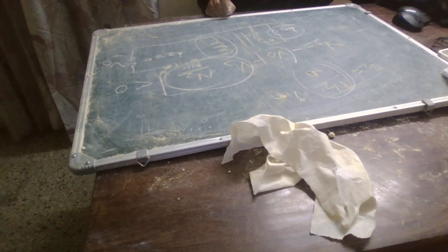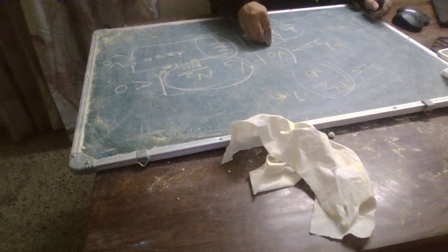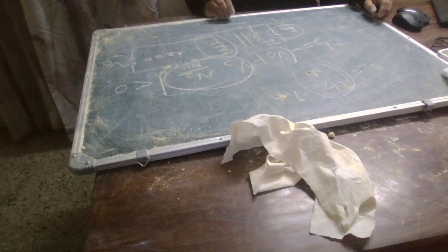One point I have already mentioned is that if saturation happens, it leads to unexpected levels of current rise. The other thing is that the flux in the core keeps increasing, that's why it gets saturated. The other point is that once the core gets saturated, it cannot support a voltage across the transformer winding.